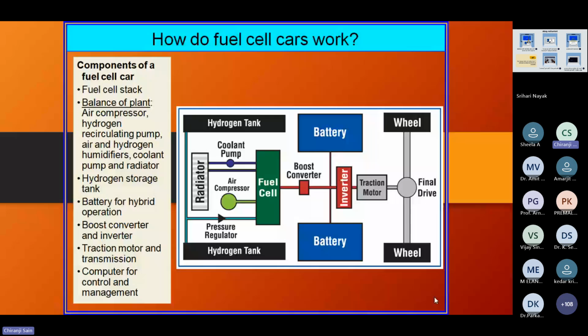That's why the direct drive motor or hub motor or in-wheel configurations of the electrical motors are nowadays being implemented, where the particular electrical motors are fitted with the particular wheels, and the speed of the wheels is the same as the speed of the electrical motors, in which manner we could conclude that the transmission efficiency of this electromechanical energy conversion system may be enhanced. And definitely, which I have not mentioned, the battery.